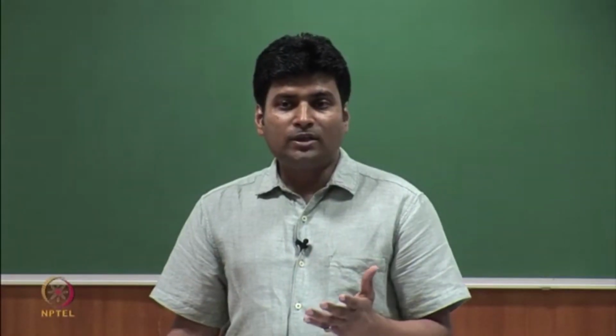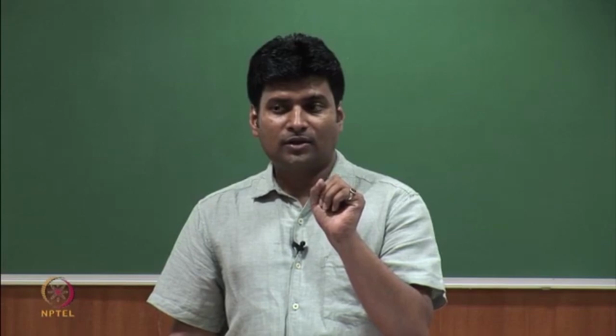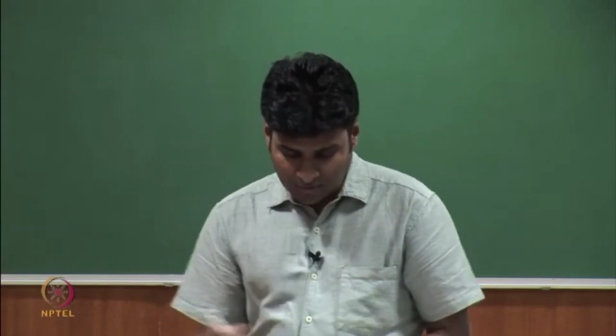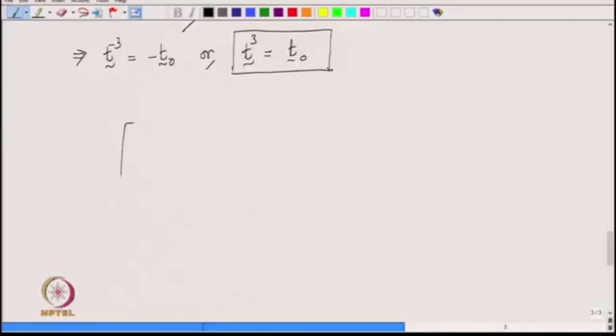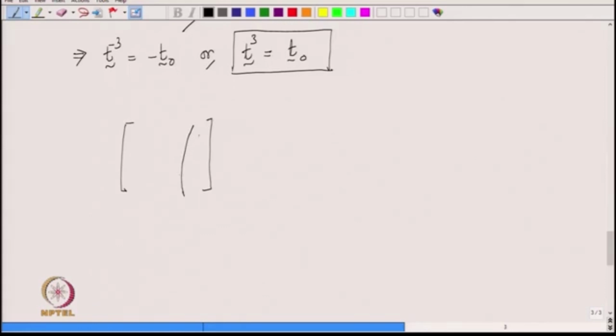So, if we now think of forming the stress matrix for a point close to the surface, what is that going to be? So, for a point close to the surface with the coordinate system that we have chosen, the third one is T naught, right. The third plane or the third column, which is formed by the traction on third plane. So, that is T naught. So, this is known to us, but what is on the first and second column, that is unknown to us.